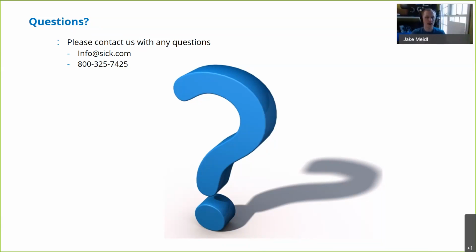On the other side of that question, if the question was more, hey, I have a standard IO sensor and I want to change to an IO-Link sensor, that's a little bit more complicated. The nice thing about IO-Link is if you have an IO-Link sensor and you want to plug it into an old system that doesn't have an IO-Link master, it actually still will function. The sensor sends out a request, and if it gets a response, then it starts sending IO-Link data. If it doesn't get that response, then it just operates as a standard digital I/O sensor.